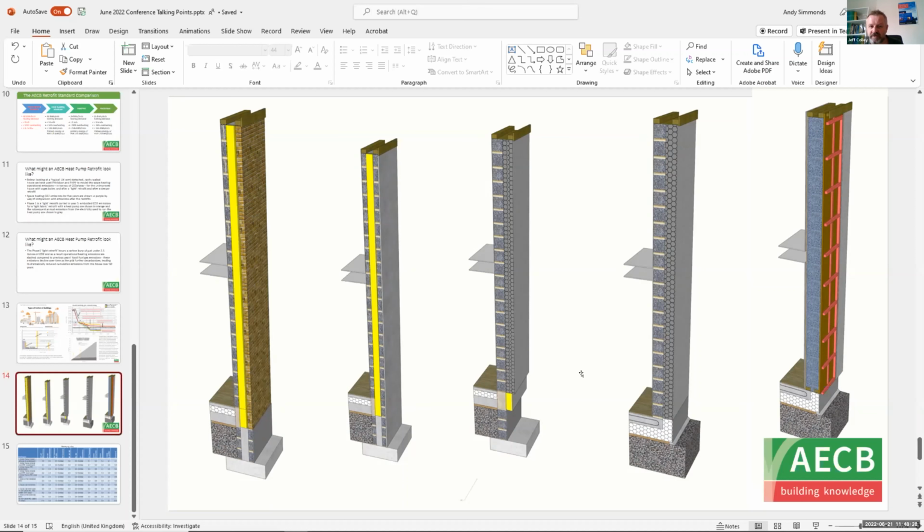So we undertook a project between the Passive House Association of Ireland, which I'm a board member of, and the AECB, a few issues back at the magazine, where we got an end of terrace house type provided by Cork City Council. John Moorhead, the Irish architect, arranged that. Initially we took 5 or 6 different wall types, and we assumed minimum compliance with building regulations. You'll notice not particularly generous thicknesses of insulation in these SketchUp drawings that Andy drew for us. We assumed a 0.18 U-value in each case, essentially.